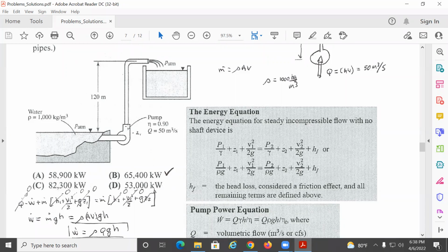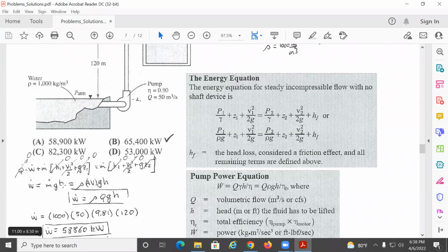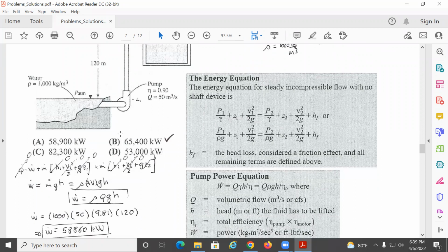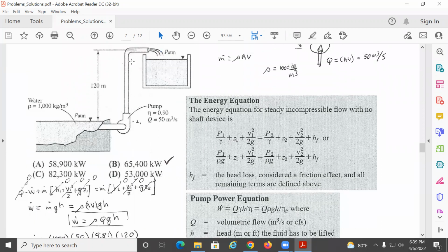But in this case, we're not interested in the H I'm talking about here, this is not mgh as a change of height. This is the enthalpy. So if we look at this equation, we have here the 0, 0, so about the H, the Z really will become the height, that then becomes the H, sorry for the notation. So this is enthalpy, and now this one will be height. If we take this point as the reference for the potential energy, so H equals 0 here, then at the inlet this will be 0, and mgh at the end will be this one over here.